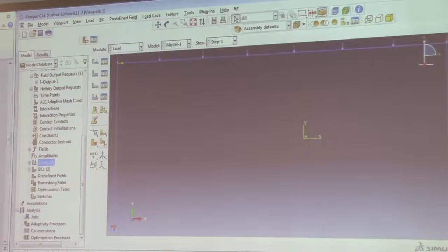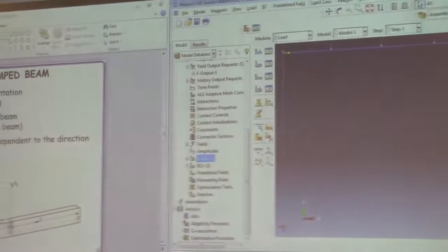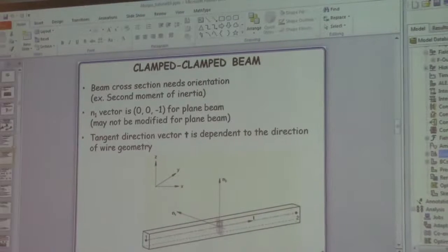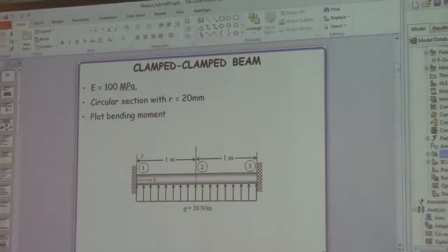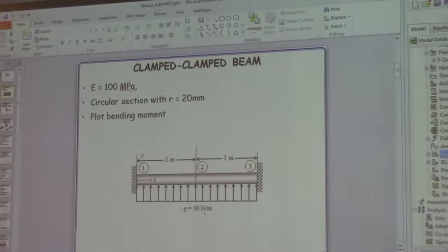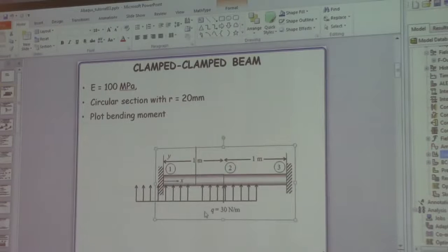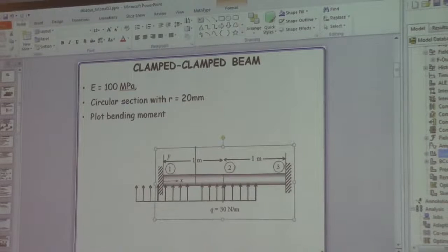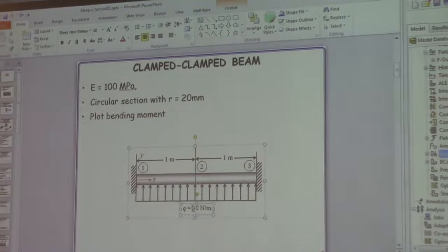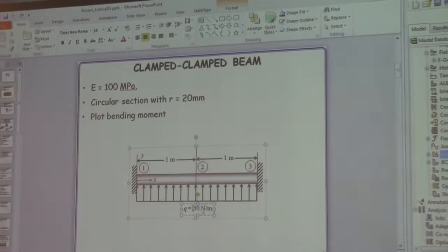And be careful when you try to do the example on the slide. It is a little bit different. It is also a distributed force, but this distributed force is given as a... Oh, sorry. What's the difference here? Per length instead of per unit area? Yeah, so the unit is different. This is a line force.